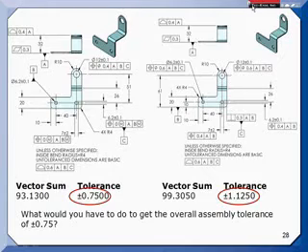Yeah, that's the one. So in this case, you have datum feature A being the face. Datum feature B is that hole, and it is not positioned to, or doesn't have anything tied into A. And I think what you're driving at is, hey, do we have to do that too? Yeah, that's a real good question, and I could be beat up for this one. Technically, B should have a perpendicularity on it back to A.